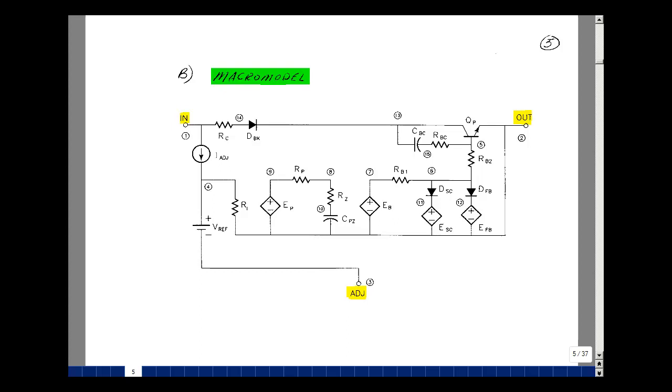And there are some things that are really handy, like an ideal voltage source and controlled sources and nearly perfect diodes if you want them. So I started out trying to model the IC by mimicking a little bit of the chip. Remember there was a picture of the functional block diagram where we had what's called a Darlington pair. It's a transistor driving another transistor to effectively make the beta F much larger.